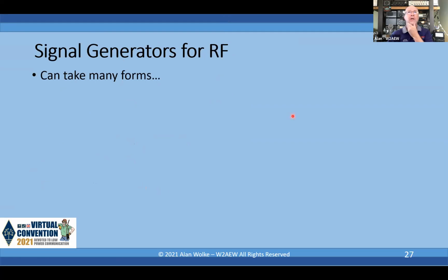So for the extra cost, Mike asks, do we go straight for a 2-port VNA? Well, anything that's labeled as a VNA will often be a 2-port VNA, but it may not be a 2-port 2-path VNA, meaning it may not have the source on both sides, and that's not absolutely necessary. A 2-port 1-path VNA, like a NanoVNA, will work very well.